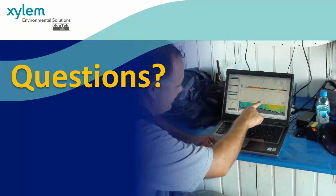Our connection to the M9 is frequently lost at just over 100 meters. Is this normal? It kind of depends. There are a couple things that happen in terms of communications with the M9 or with the RS5 too. The line of sight is extremely important, and for the frequencies used for communications, if you're using the most recent PCMs that use the 2.4 gigahertz frequency, this is a Bluetooth frequency, so it's pretty heavily attenuated by water.